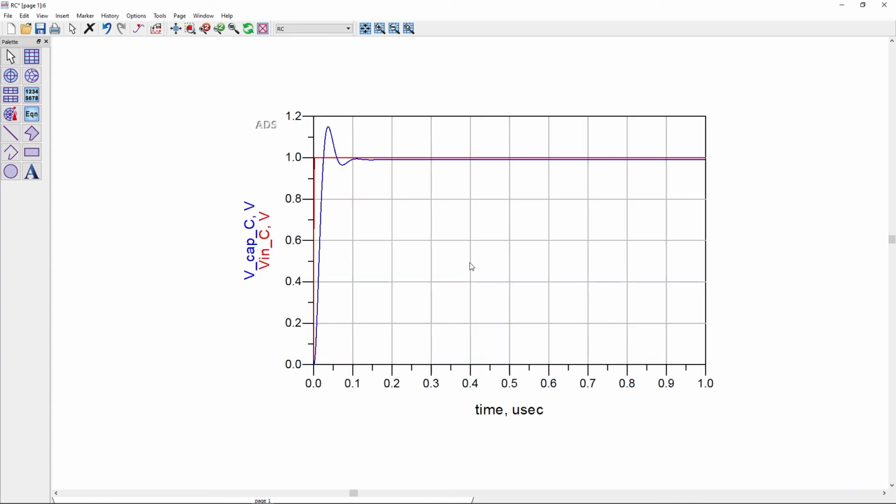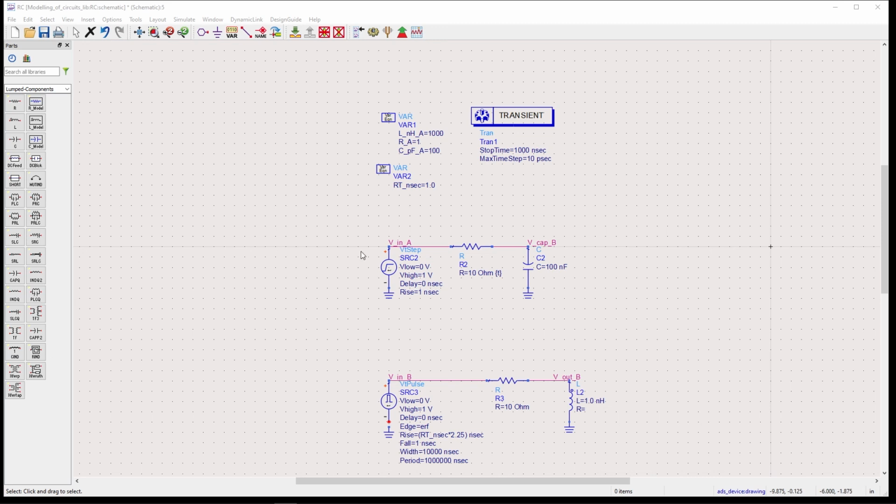For the second graph, I still need to do some consistency checks to make sure what's going on. But in this particular case, I know there should be some oscillations based on what we've modeled, but the values are not exactly the same as what I did in MATLAB. The reason is the nanofarad and picofarad scales, and my simulation is also running in a different time interval. In MATLAB I was just able to put in the numbers and it would work, whereas here it's looking at every instance of time and trying to sample how the circuit would behave.